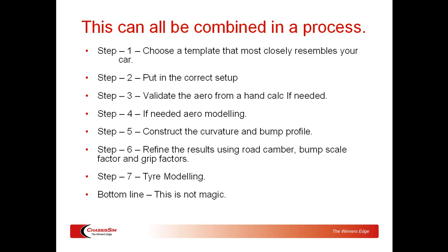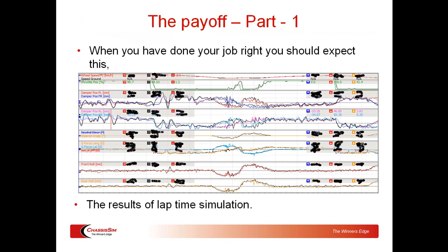You construct your curvature and bump profile. You refine the results using road camber, bump scale factor, grip factors, and your tire modeling. Bottom line, folks, this is not secret squirrel stuff. This isn't black magic. It is a process. And once you get used to this process, it will transform the way you engineer a race car.